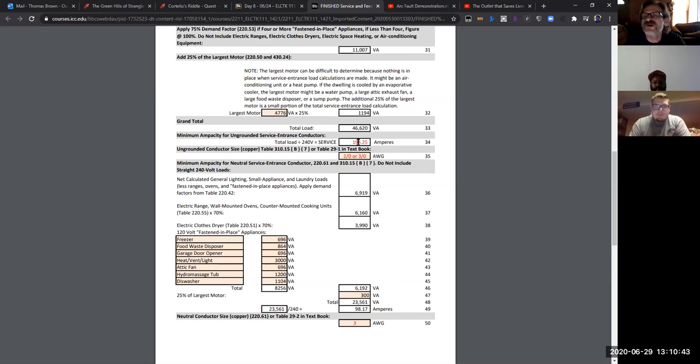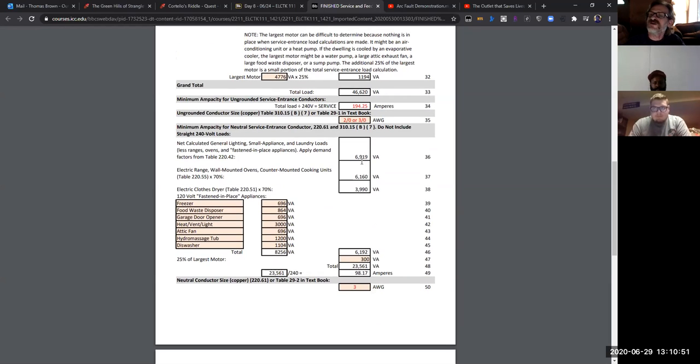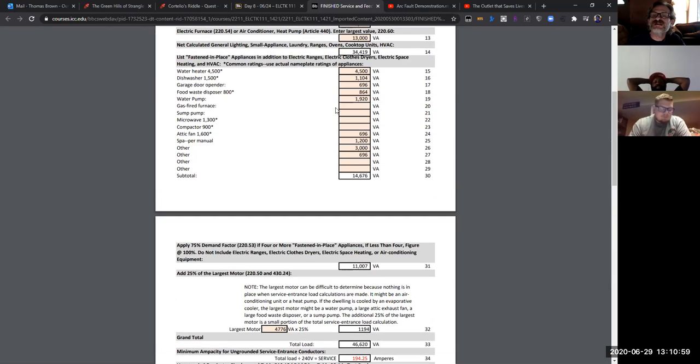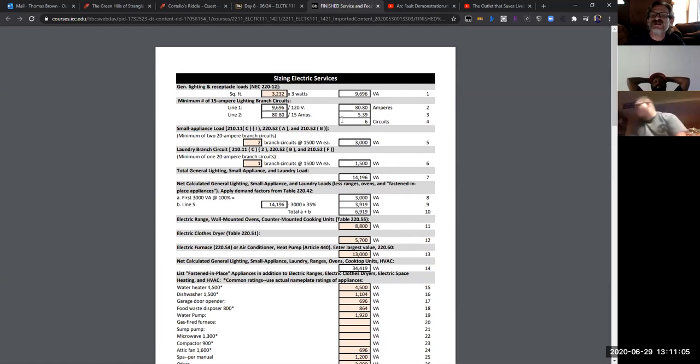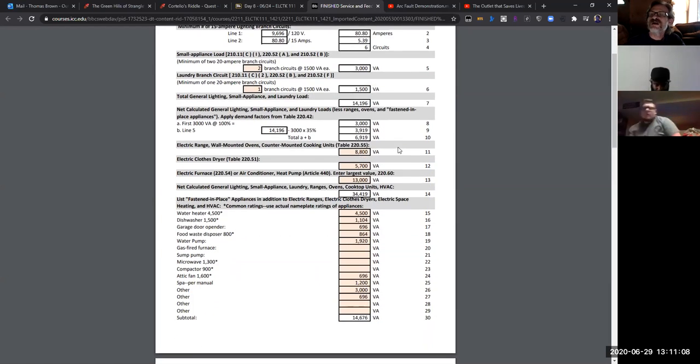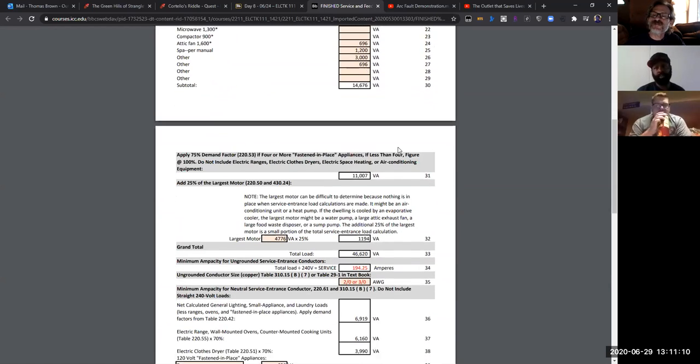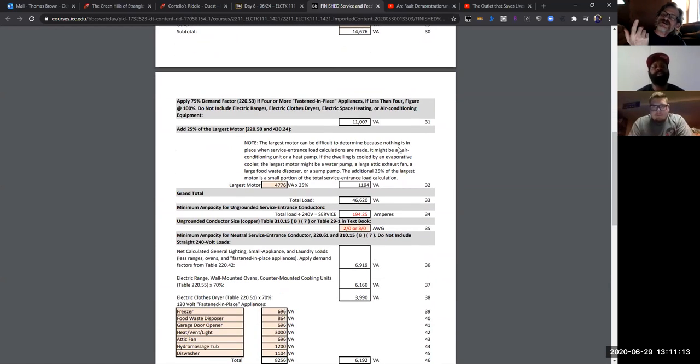So in this case, we need a 200 amp service panel, right, with a 200 amp main breaker on it. And so this is all what you're beginning with, or what equipment we're going to have to put this service in. And then we'll be able to size through, and based on this, how many breakers are we going to need? How many branch circuits we're going to have installed and all that. So pretty much what this will do is you'd be able to set up and buy all your stuff for your service entrance, getting all your circuit breakers purchased at this point and stuff like that.